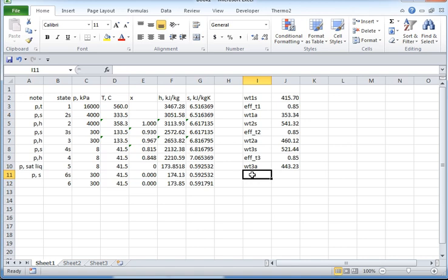I like to use equal to so that I'll have less typing in of numeric 300. Okay, so we have the work pump 1 isentropic. What is it? It's equal to this H minus this H. True? Okay, so about 0.2, a whopping, wow, 0.2 kilojoules per kilogram. You have the efficiency of pump 1, 85%.